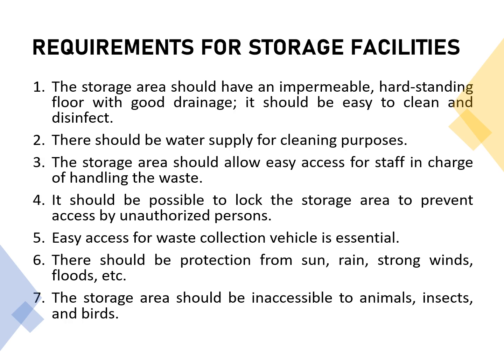So what are the requirements for storage facilities? We have the following. Number one, the storage area should have an impermeable, hard standing floor with good drainage, and it should be easy to clean and disinfect. And this is in relation to number two, there should be constant water supply for cleaning purposes. In cases wherein healthcare waste containers have leaks, you can easily clean the spills using water, and the purpose of the drainage is to not accumulate water in the storage area.